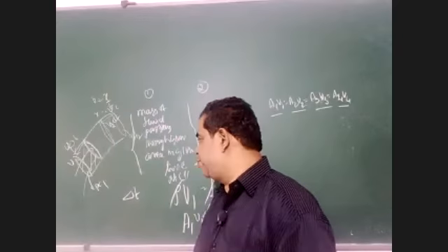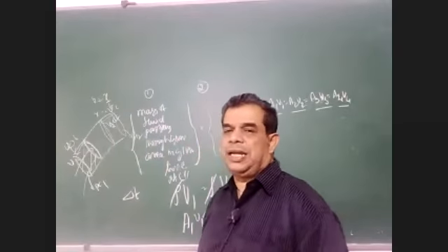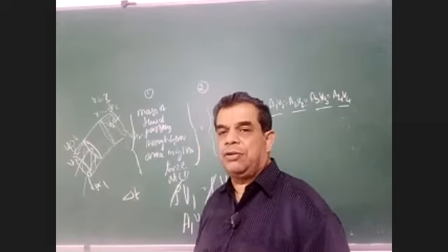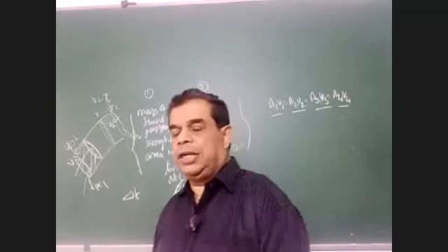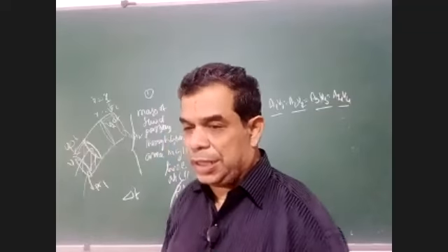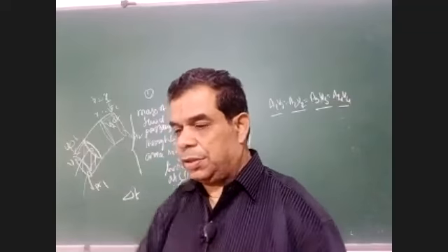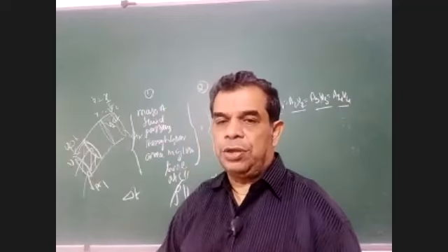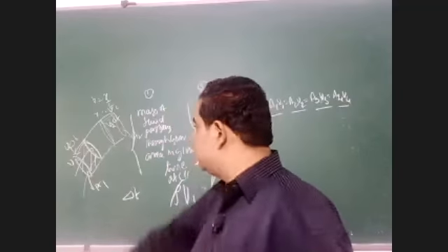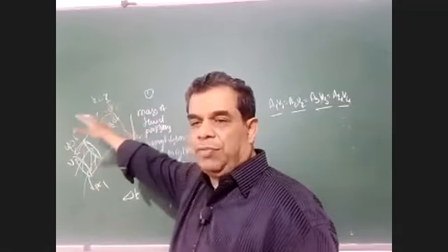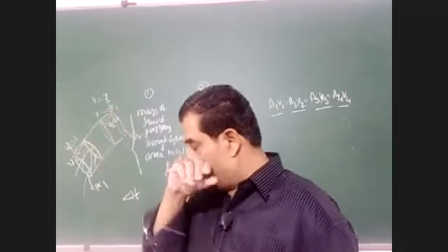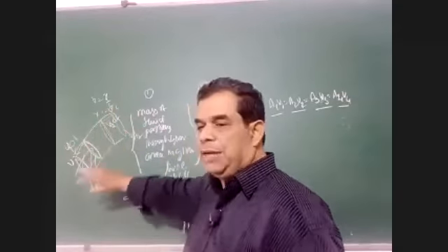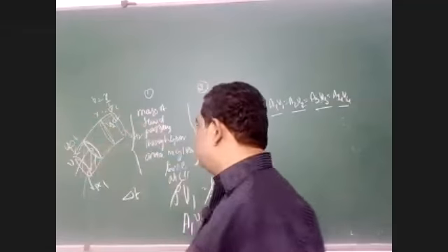By the time you conclude, if you write the answer for this question, I will conclude after this. So I write down: derive the expression for the continuity equation. But observe what to write as a preamble sentence. First draw the figure, one streamline flow figure, and then show 2 areas, A1, V1, and A2, V2 velocity, like that.